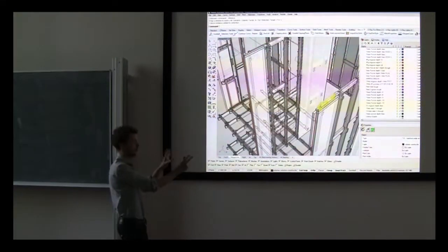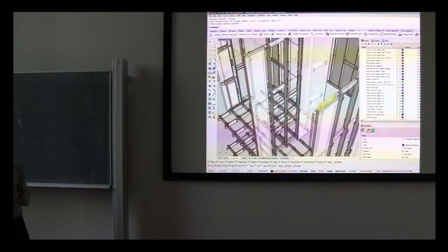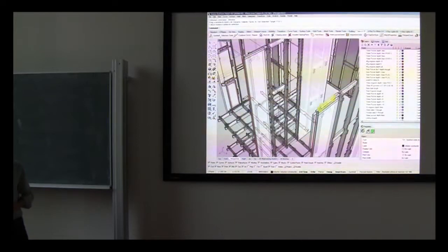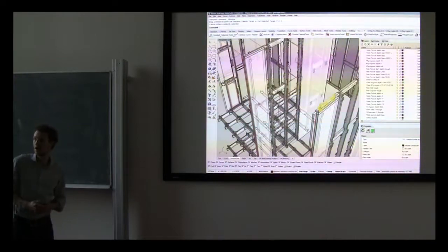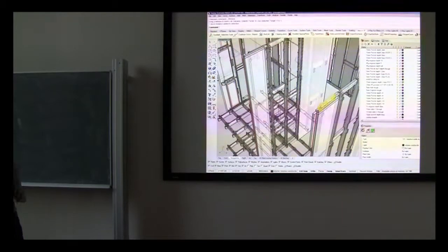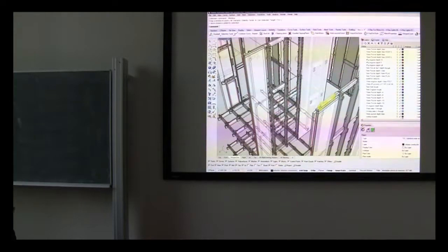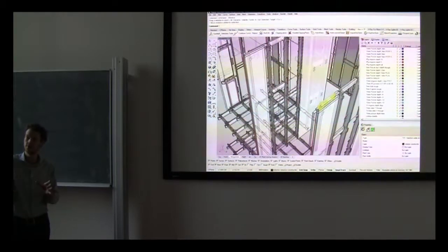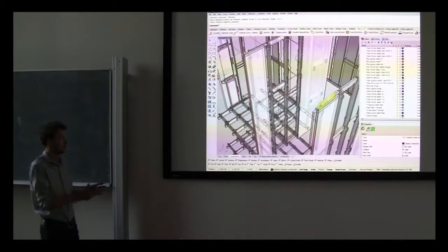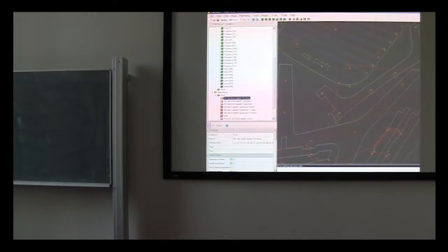You see that this is, for example, such a model. We have all the knowledge of every square millimeter and also all the influence of every square millimeter of the design. And what you see is that in such a very well integrated process, we are able to eliminate the failure costs. In the current building industry, the failure costs are on average 12%. That's really huge compared to other production industries. And we try to bring it down by using a fully digital design, engineering and production process. So this is basically the file to factory process.